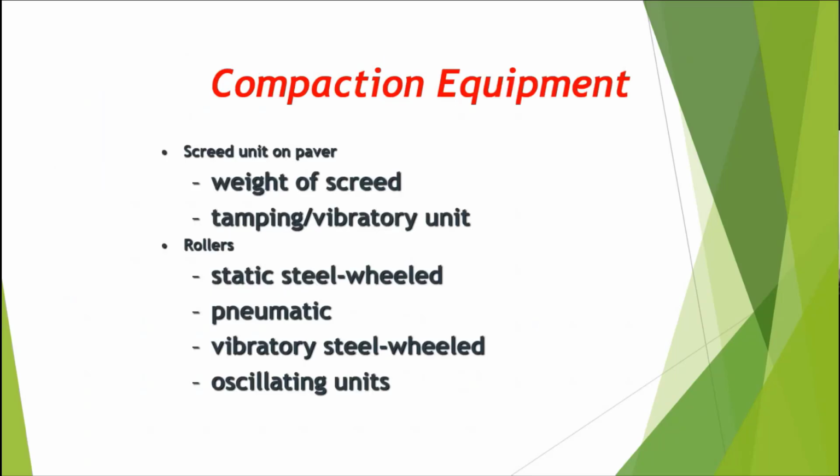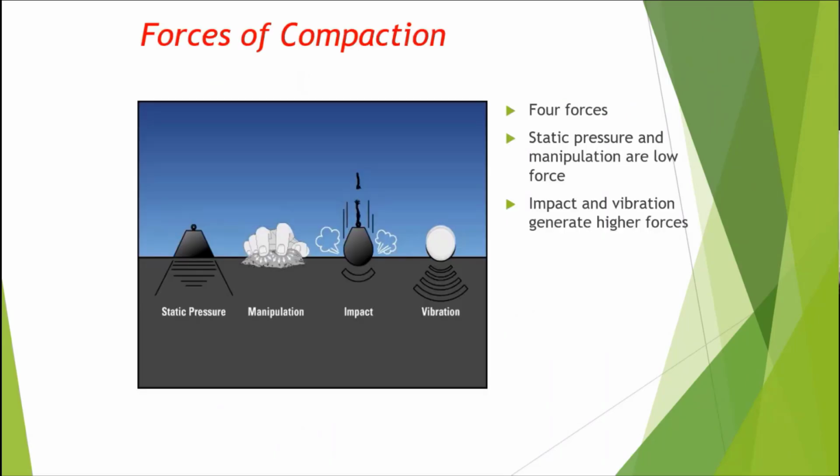One big improvement, the first piece of compaction that we do is actually in the paver. It's on the screed. And you've seen over time now, particularly with increases in ride incentives, heavier and heavier screeds going on pavers, which generally leads to heavier and heavier horsepower on the paver. And now, can't remember, it used to be called a DMX screed. We're seeing those introduced to the market, a little different than a smooth steel screed.